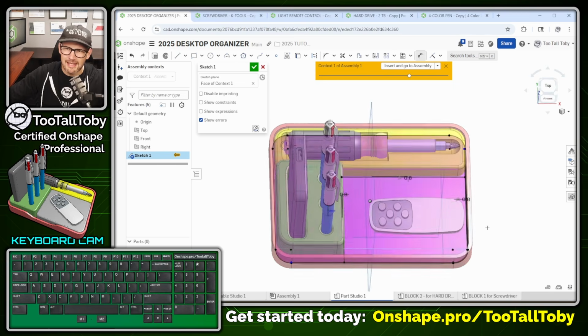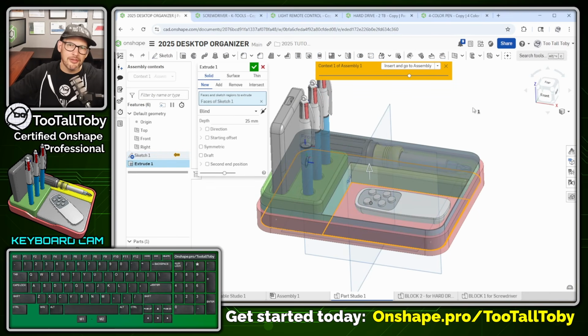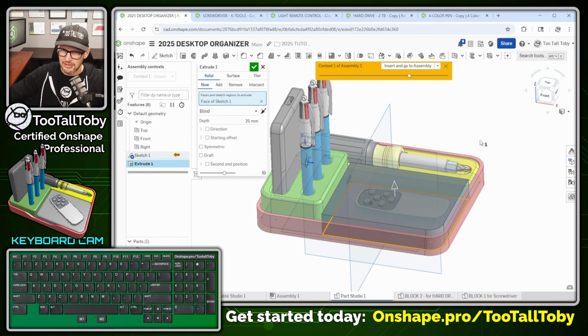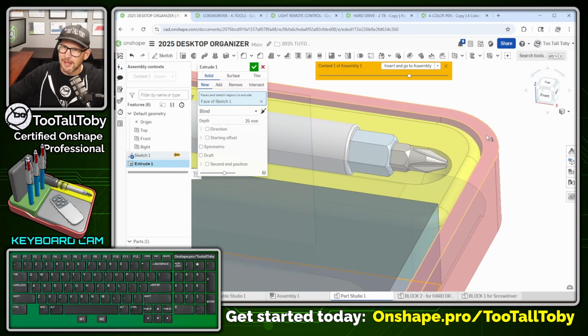And so now we can take that geometry and we can choose to extrude it. Now, the first thing I'm going to do here, I always forget this step, but I'm just going to click in the background and press space, clear my selections, and then I'm going to pick this region here. So I'm extruding the correct region. Now, in our previous example with the yellow block, what we did was we extruded it up to face and we picked that face there.